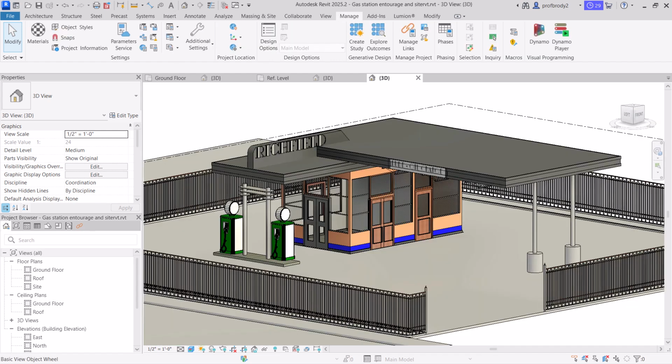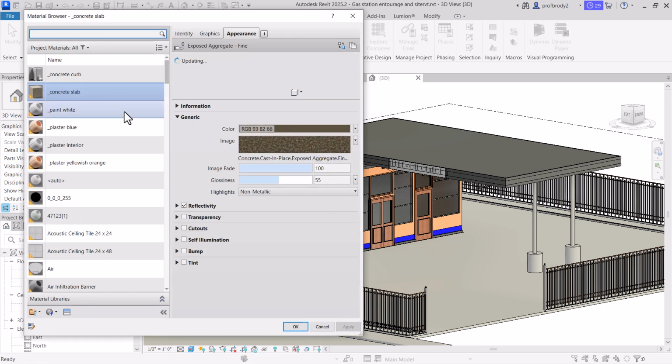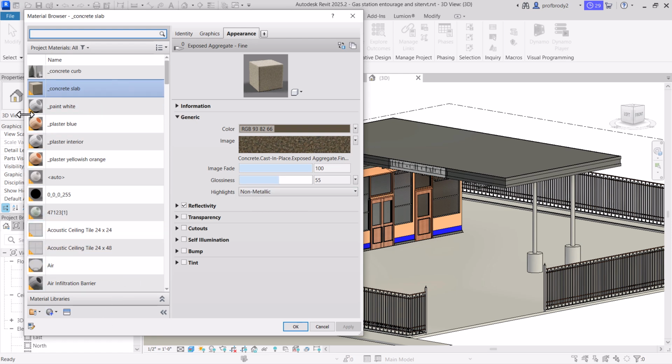So the last thing I'd like to do is apply paint to all the different surfaces of the model. And who doesn't love the paint bucket? That's probably the easiest way to go, or at least for some surfaces. And the advantage of the paint bucket is if you have created a paint in your project, and it doesn't have to be paint, it can be concrete, as you see here, you can just choose it and dump the paint right away.